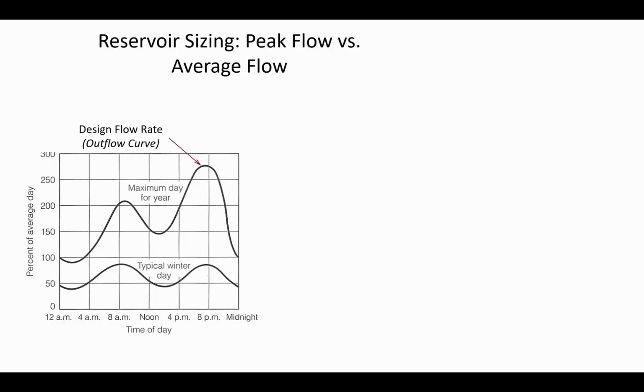We're going to put enough volume into that reservoir that at night it fills up, and during the day, when there's a high demand in the city, the tank is going to drain. And the reason why is that during the day, there's more flow coming out of the tank because of those really high demands than there is flow coming in. So this blue line